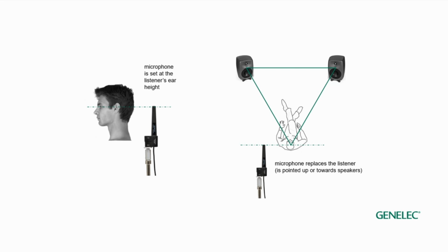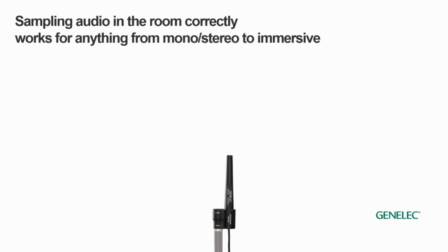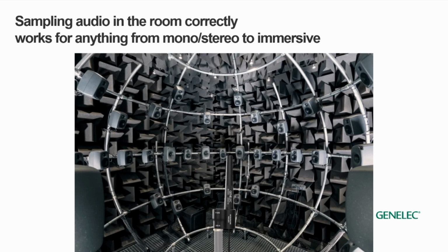Because the microphone has been designed and calibrated to work when it's pointing upwards, it means that all directions around the microphone on the horizontal plane have exactly the same frequency response to the microphone capsule. For immersive systems, the higher and lower monitor layers have the same frequency response at the microphone in the frequencies where GLM4 is performing the automatic calibration.